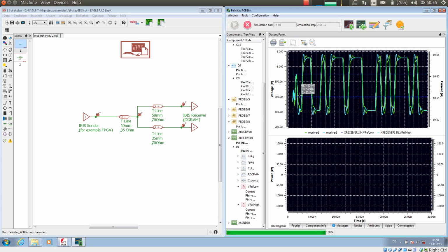This is of course the case because we have approximately an output of 34 ohms. We have a transmission line of 35 ohms. We have this transmission line split into 2 lines of 70 ohms. So again, we have a match here. And then we have an on-die termination of approximately 60 ohm. So this is all perfectly matched, and it gives a very nice simulation result.